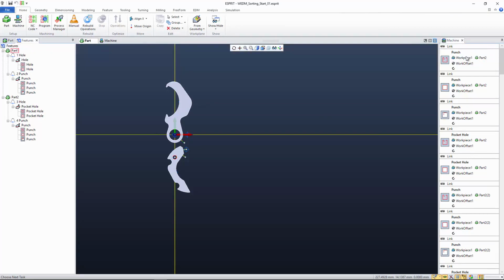So as I mentioned, we can manually select things and move them up and down the list. You can see I no longer have any restrictions on where I move these items. So you have to be a little bit careful, because although we do provide you with the freedom of moving things exactly where you want them, you could end up with a scenario where, for example, the cutoff of my punch is moved before, say, the rough and the skim, which doesn't make much sense.